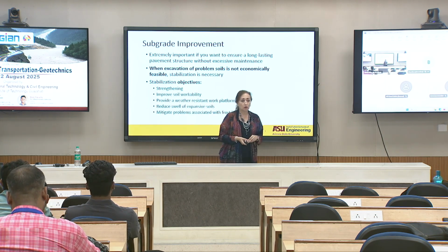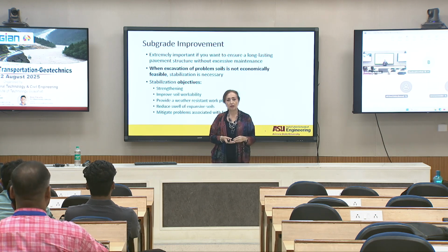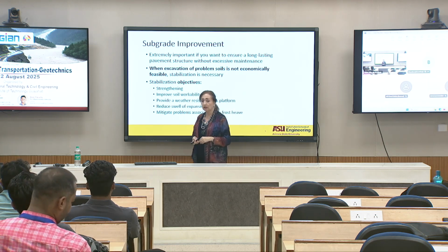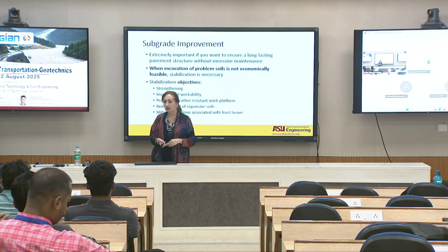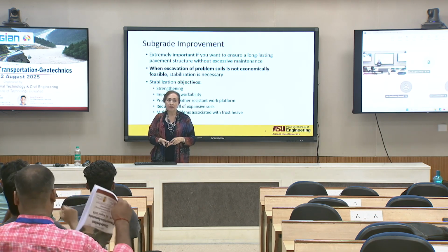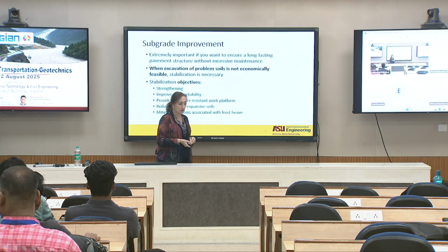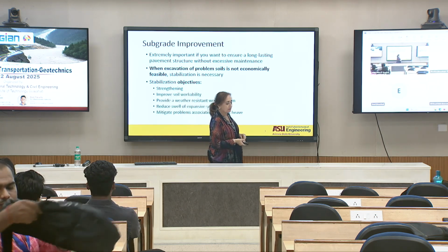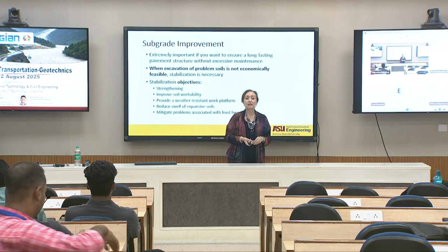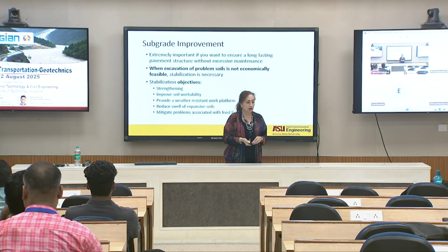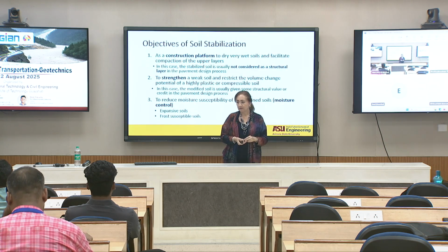Weather resistant work platform also goes into the workability at the construction stage of your road. Swelling, or volume change: reduce swelling on expansive soils that you've seen the problem around, and also mitigate problems when we do have frost heave.